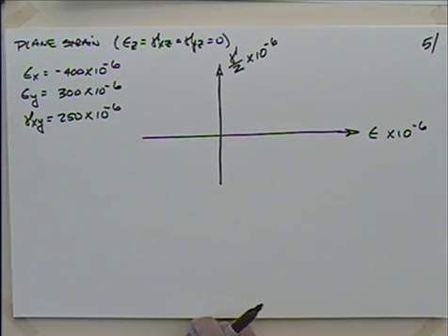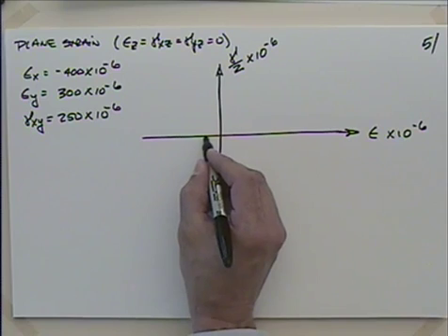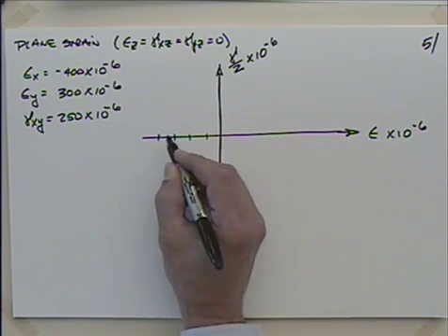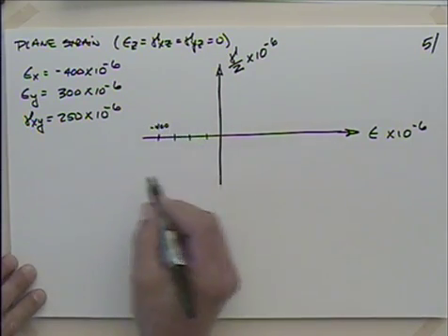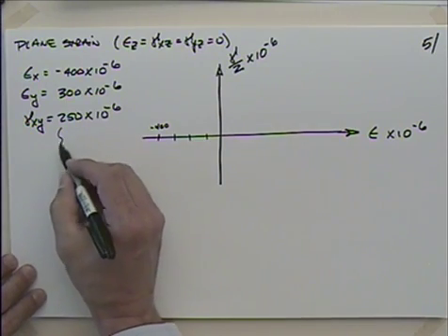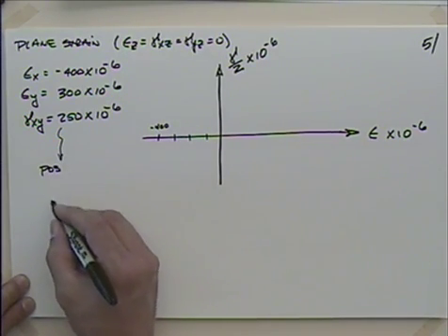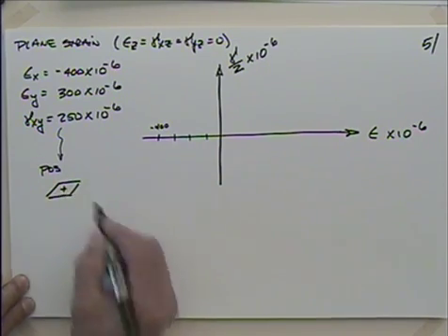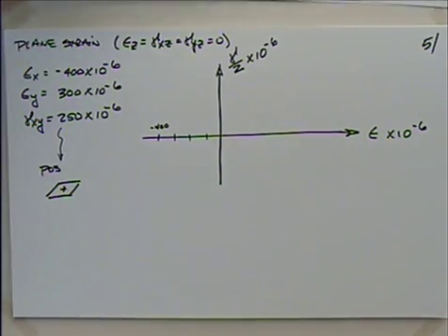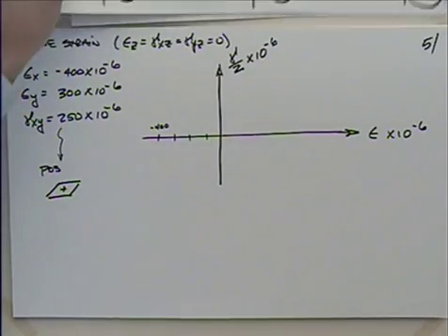So if I look at the x face, what do I have? I have minus 400, so that is definitely negative, isn't it? So I'll have 100, 200, 300, 400. There is minus 400. And then this gamma xy, that's a positive number, isn't it? If that's positive, what are we thinking? It probably has deformed it like this, hasn't it? Is that consistent with what I just got done talking about? Yeah, right here.